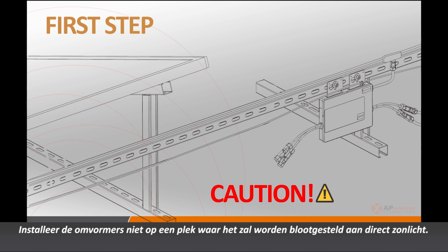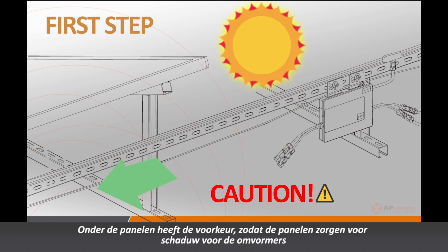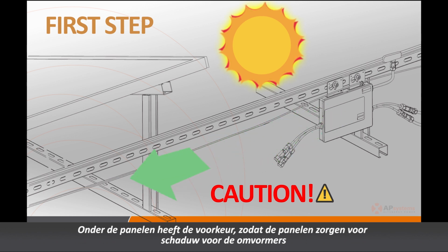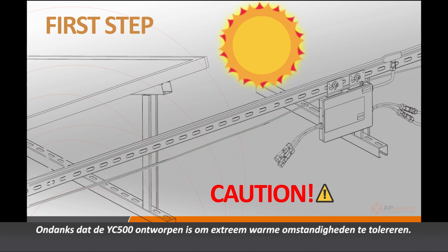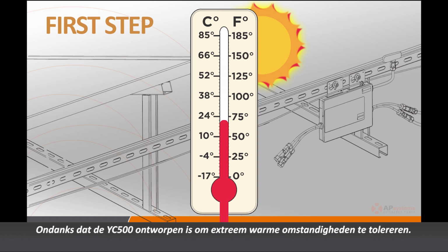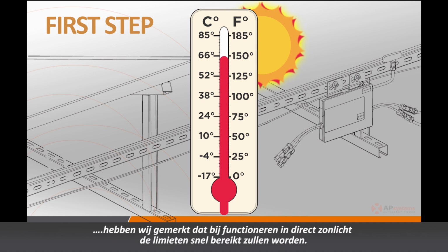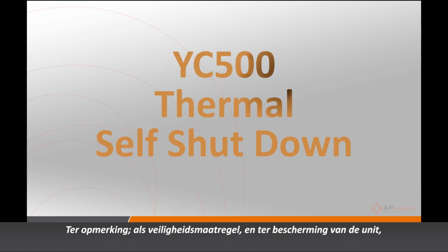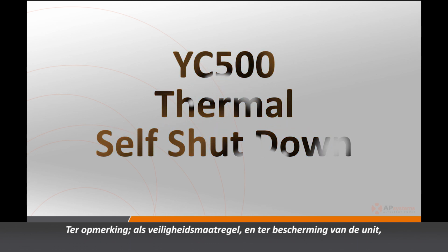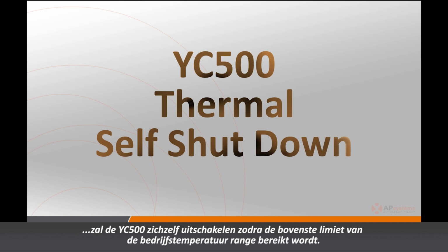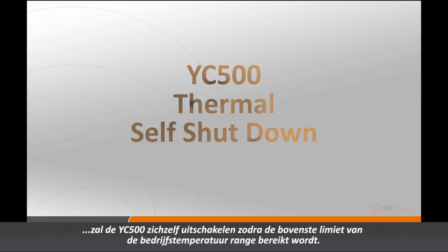Do not mount the inverter where it'll be exposed to direct sunlight. Under the PV panels is preferred, where the panels are providing shade for the inverters. While the YC500 is designed to tolerate extreme heating conditions, we've found that operating in direct sunlight will quickly push those limits. Just as a note, as a safety measure and out of self-preservation, the YC500 will shut itself down when it reaches the upper limit of its operating temperature range.